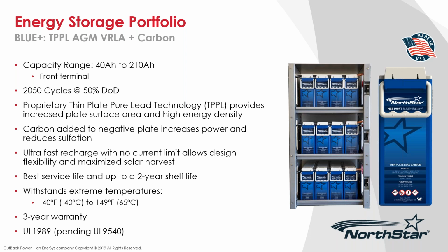So some people say, well, I'd rather go big on solar, self-consume, net meter the rest to the utility, and just have a couple strings of batteries. What's nice about PLR and Blue Plus is you don't have to worry about overcharging the batteries. As compared to the SimpliPhi lithium batteries, there is a formula in our application note as well as the integration guide from SimpliPhi that specifies a minimum number of batteries for a given charging source. In other words, you can overcharge the SimpliPhis if you have too much solar. So that's something to keep in mind between these batteries.